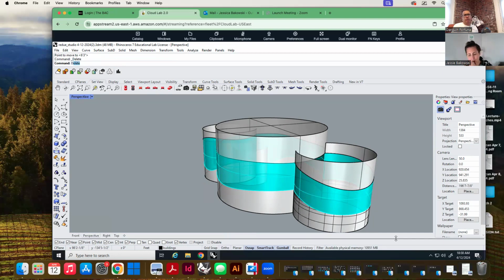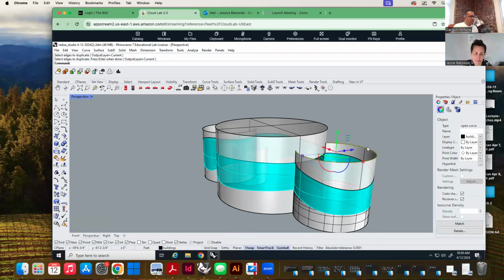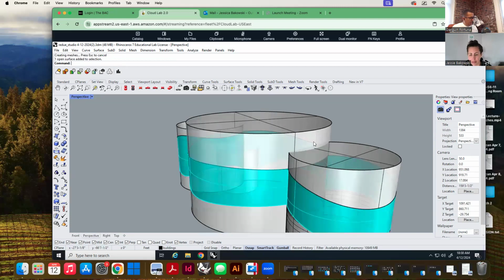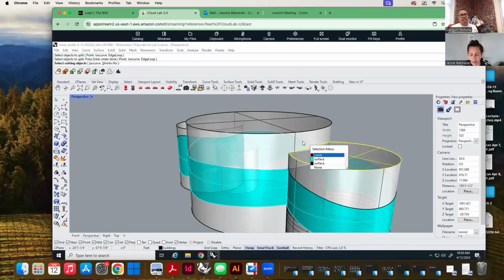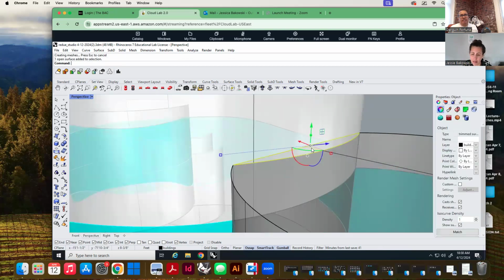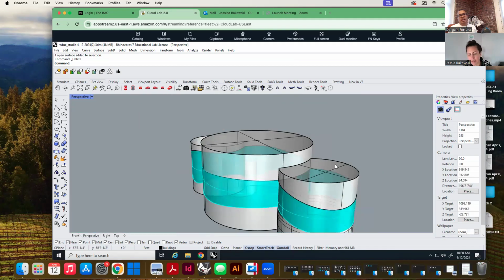Yeah, but by the way, very quick. The roof, all you're gonna do is the following. You're gonna say close curve. It's gonna close the curve. You're gonna plan out the surface. It's already bigger than what it needs to be. You're gonna split that roof using this, and it's gonna cut it. And that's it. It's simple. You just have to make the roof bigger than what it needs to be. So you just use the close curve command? Yeah, I duped the edge and then said close curve. It closed nicely, and then I just split it with this piece.